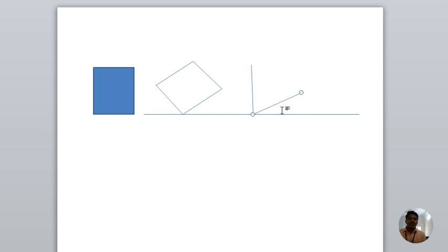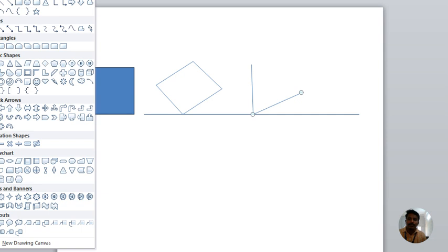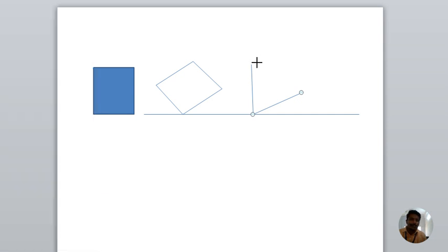And here, the drafter is fixed, with one edge parallel to this line, and draw the 40 mm line at this point. With the help of the ruling ruler of the drawing instrument, we should draw the parallel line of this line, and to this line draw the parallel line from here.